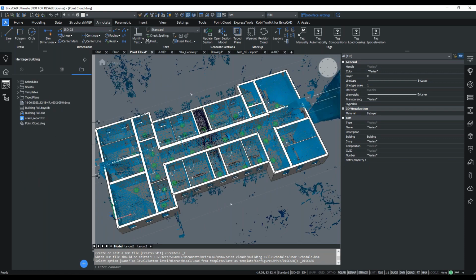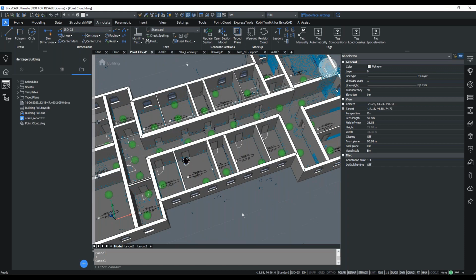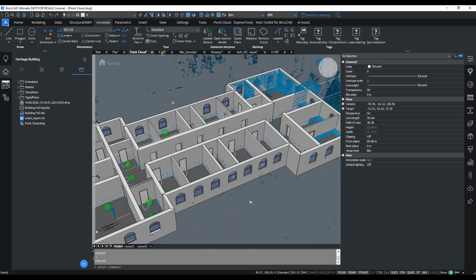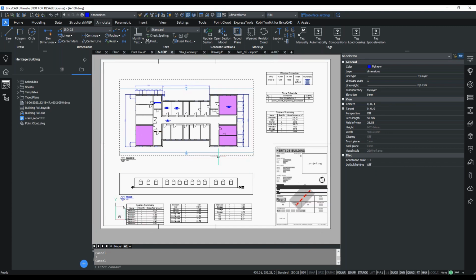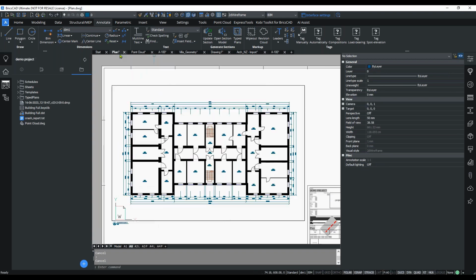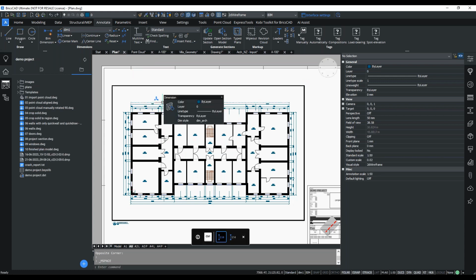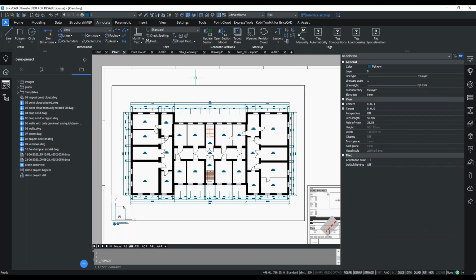And this was where we did the same geometry as I went through in this webinar, but we put some more effort into it where we extracted all the walls and all the windows. So once that was done, we ran the automatic version where we produced this BIM type output where these dimensions are in paper space, but they interact with the model space version. We also show that if you wished, you could go and do this manually, where you got your existing dimension styles. So your drafting team can just take that geometry and work through those areas.